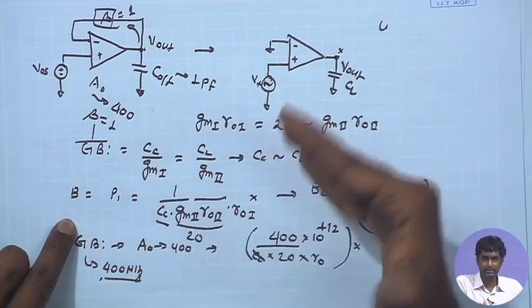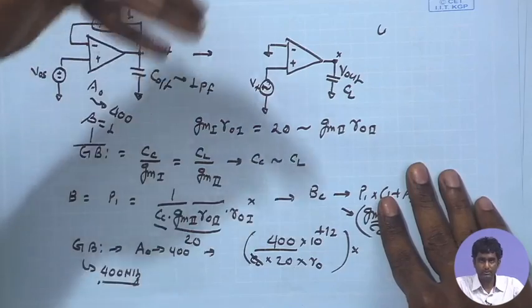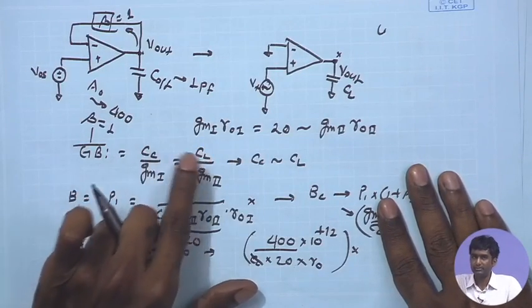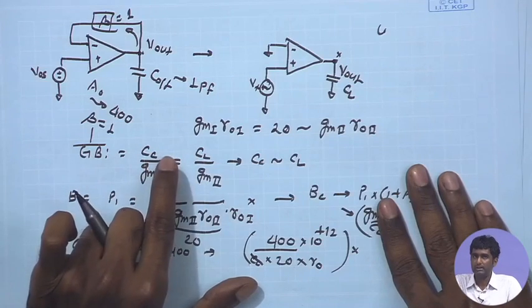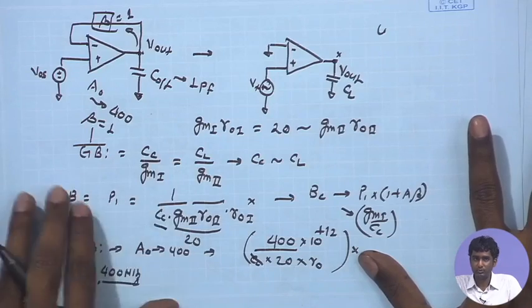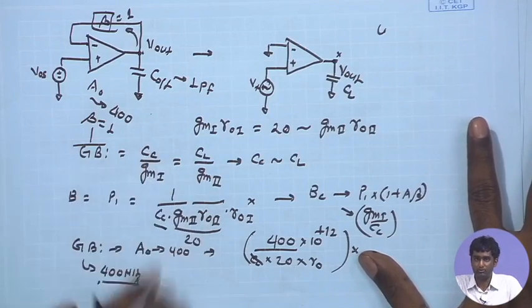CC and CL are getting determined by the constraint on the sampling capacitor. We want it to be sufficiently high so that leakage and other non-idealities do not affect it. That is determining a large magnitude for the CL and hence CC for 45-degree phase margin. Once the CC is known, we know the bandwidth is going to be determined by the CC and the GM-RO of the first stage.